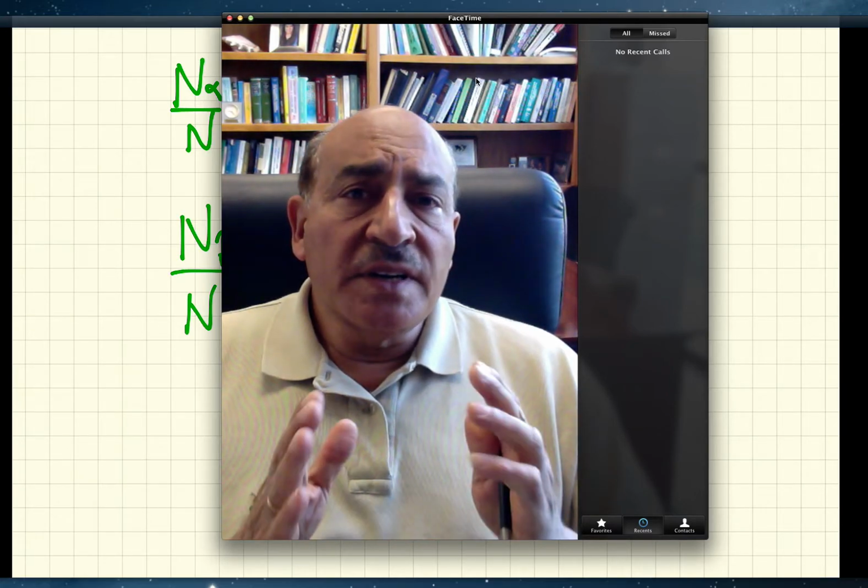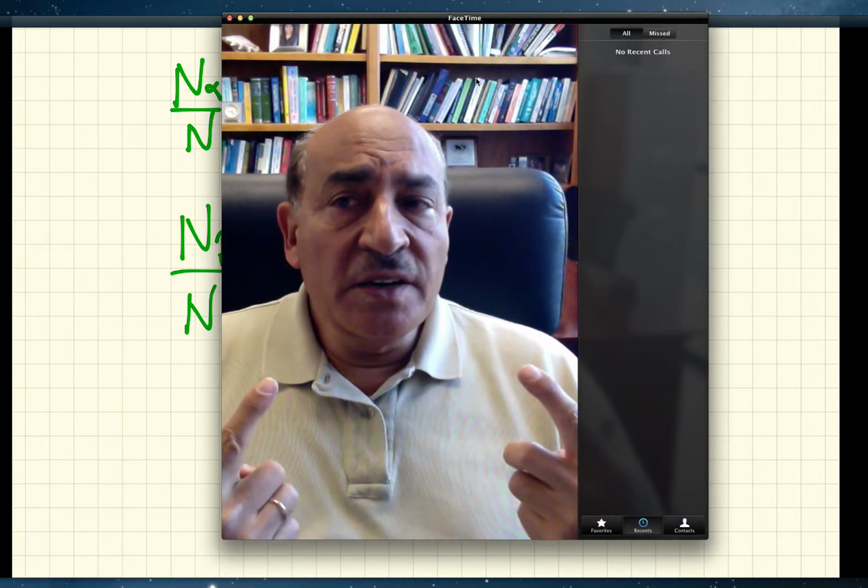So next, okay, we're all done, because if we have the phase boundaries, we can represent them by straight lines, and we know the initial concentration x0. We take the moments about one side or the other, then we can find the corresponding concentration in phase alpha and phase beta. Notice that all of this is dependent on one of the concentrations, the x sub b, for example.